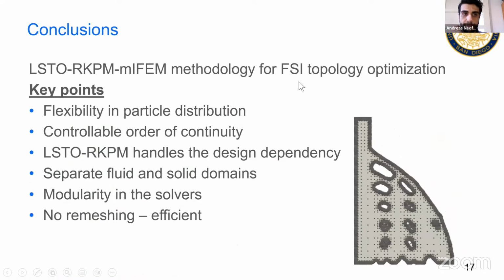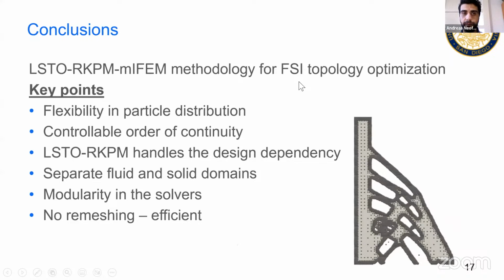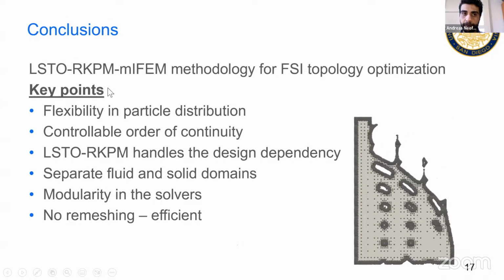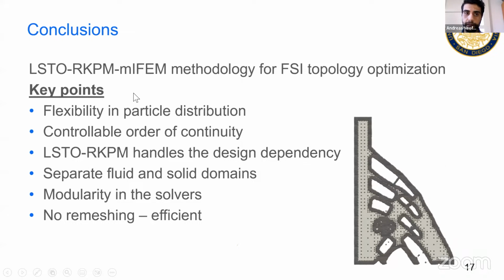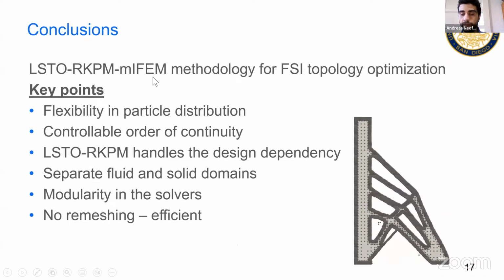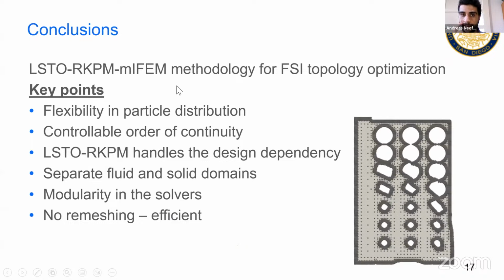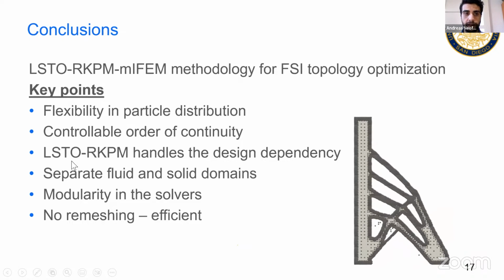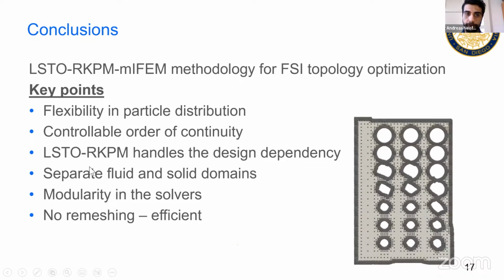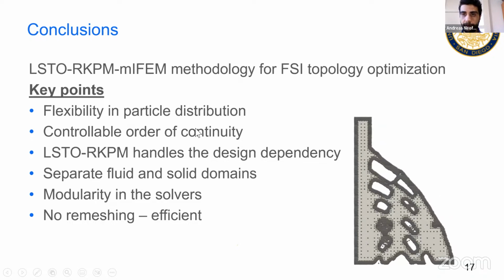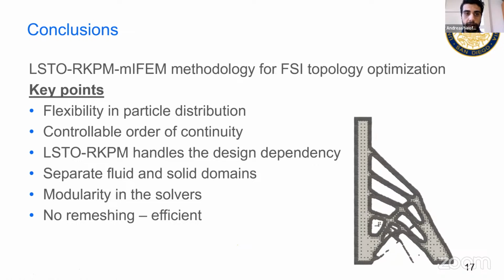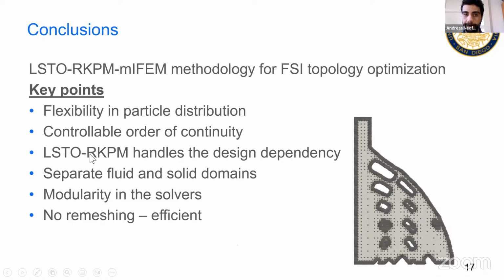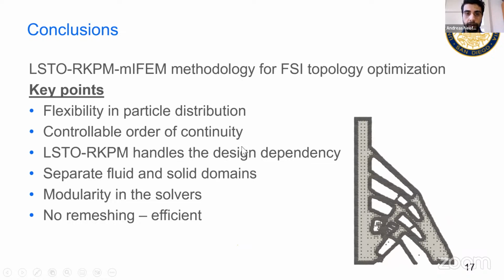Overall, to sum it up, we have developed an approach for fluid structure interaction problems in topology optimization. We combined our level set method with a particle-based approach for the solid domain, and we used the modified immersed finite element method to do the FSI analysis. We see some key points in this methodology. From the point of view of the solid, we have the flexibility to lay particles in the domain freely. We have controllable orders of continuity, and this gives us a way to directly address the design dependency.